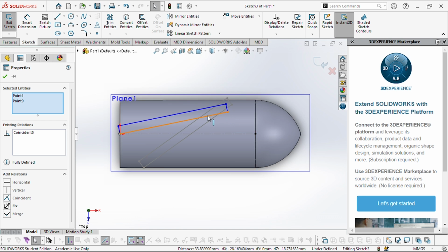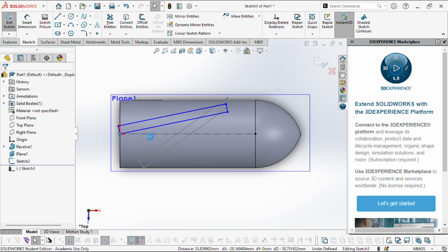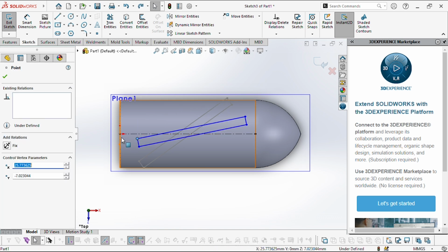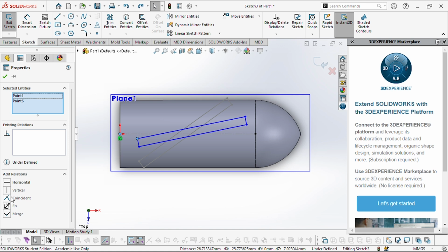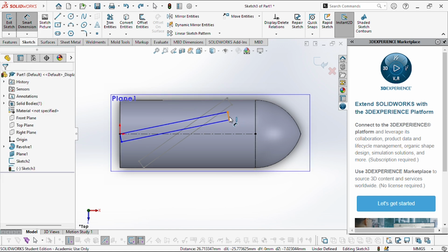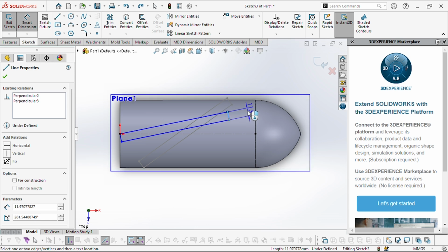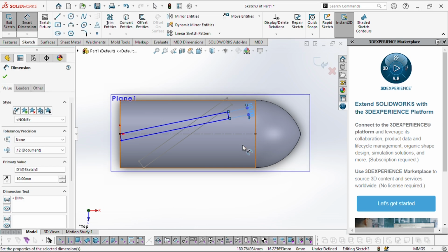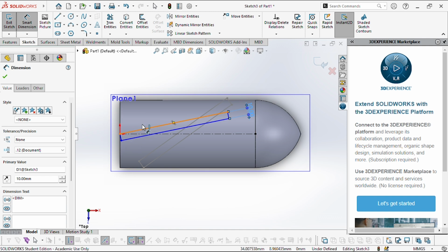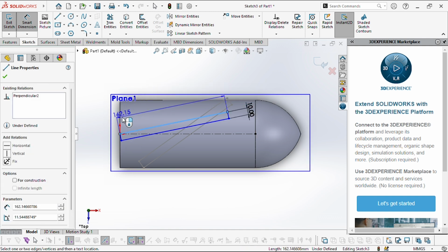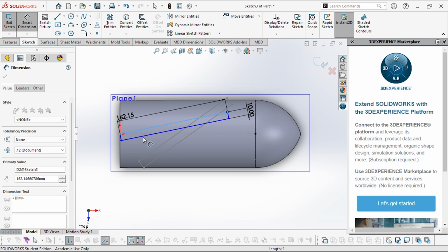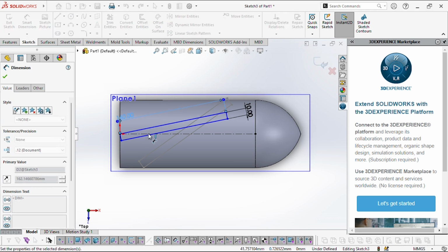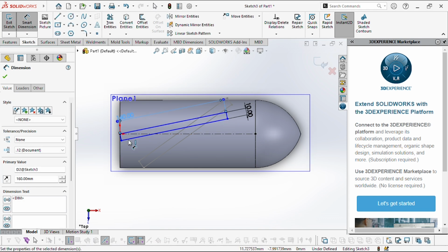So I had to undo that, then do the relationship from the top edge, so that everything will be in the shaft of the propeller. Then I continued with the dimensions. That's when I wanted to dimension everything accurately to fully define the sketch, and it was still underdefined.